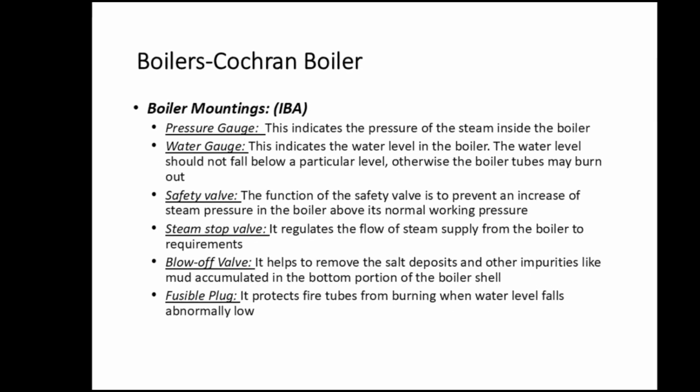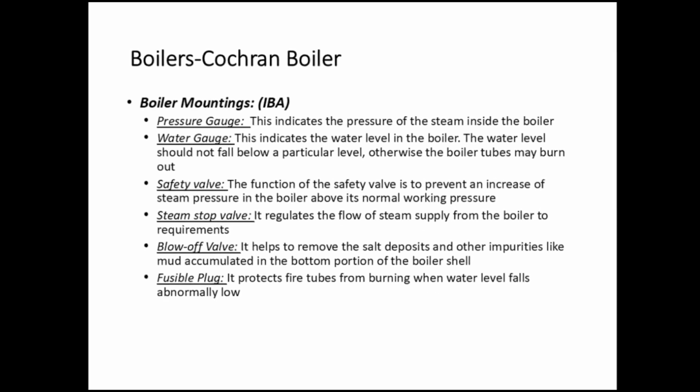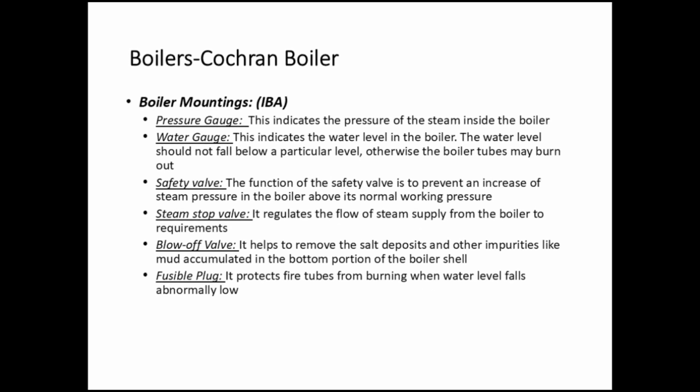Pressure gauge. This indicates the pressure of the steam inside the boiler. Water gauge. This indicates the water level in the boiler. The water level should not fall below a particular level, otherwise the boiler tubes may burn out.